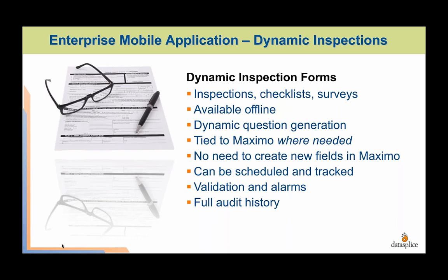We have validation and alarms. If you enter a pressure reading that is just ridiculous, it will tell you so and say, try again, bozo. If you put a reading in that could be real, but there's a problem, too high, too low, it can pop up an alarm, record your messages, and even from there go out and create a work order directly. The conditions for those can be just about anything you want. We have some simple ones. You know, if it's this, do this. If it's not this, do this.